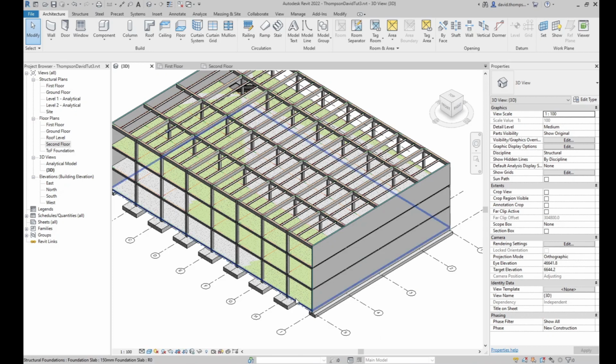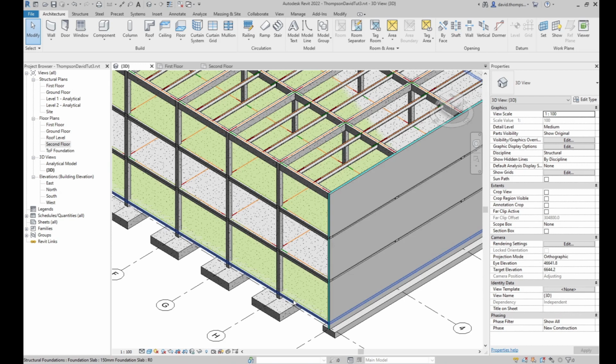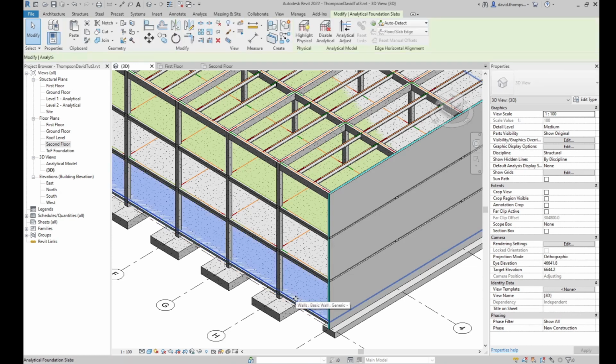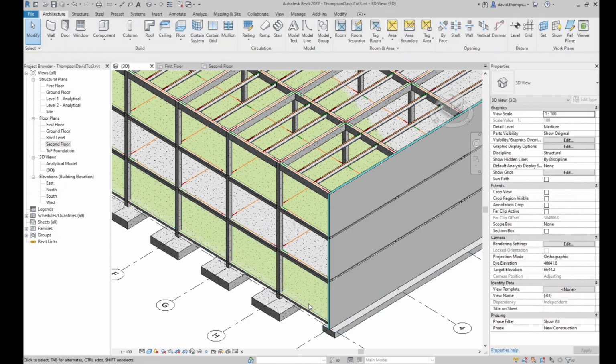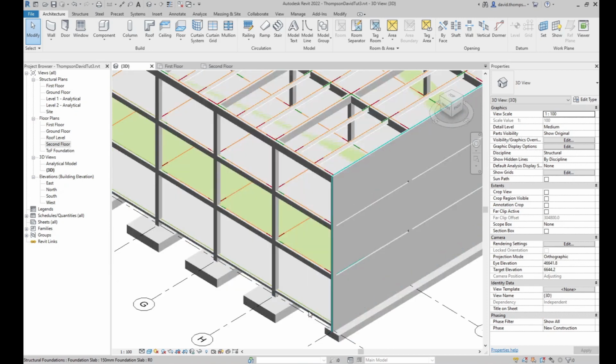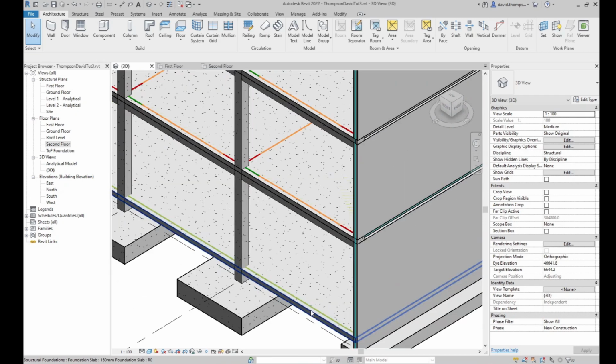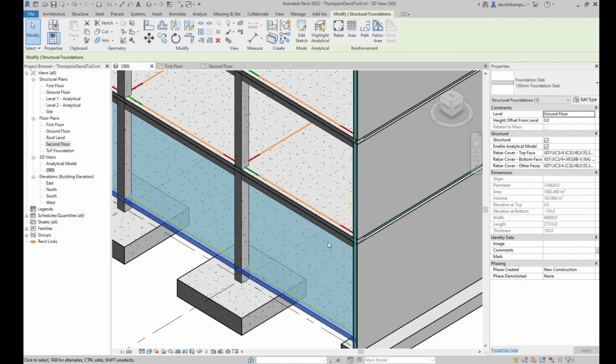Again, just go in here and select your floor. You can just hover over it. Once it's selected, you'll see it's there. Make sure you actually get the floor, not everything else surrounding it. It can be hard, so I have to zoom in a bit. Okay, here we go. Once it's selected properly, it'll go slightly transparent and it'll be the only thing selected. If you come up and the edit tab is grayed out, that means you've selected one or more elements instead of just the floor.